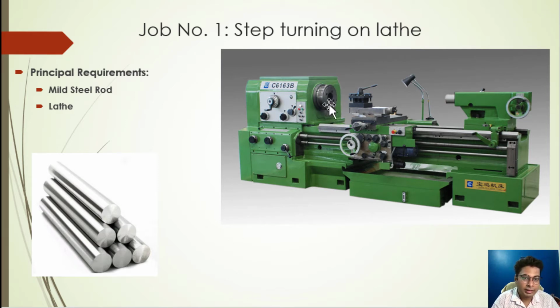Either they are held in the chuck or between the two centers, and then turned against a single point turning tool or single point cutting tool. You can see there is a tool post where a tool is mounted. How a tool is mounted and how it takes part in cutting action, we will be seeing in the next slide.